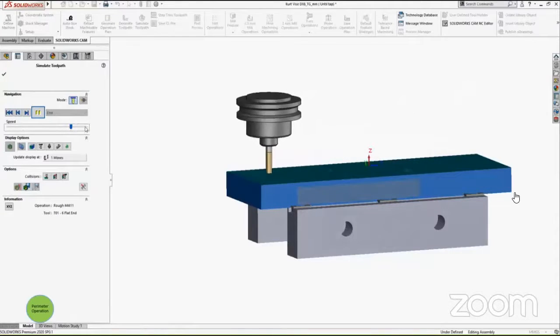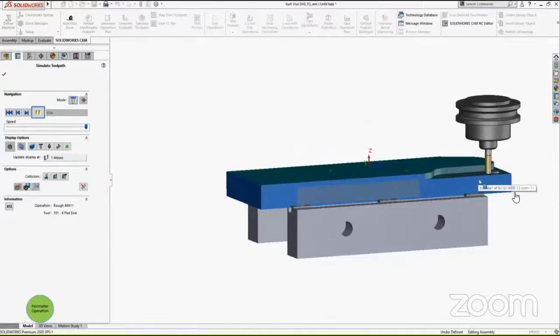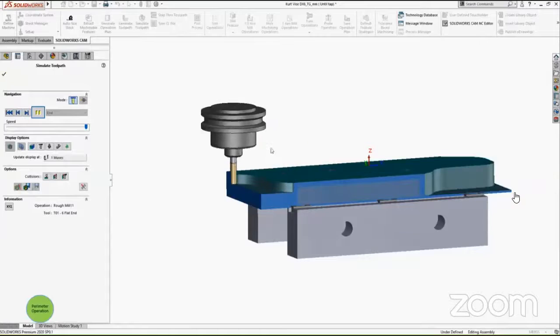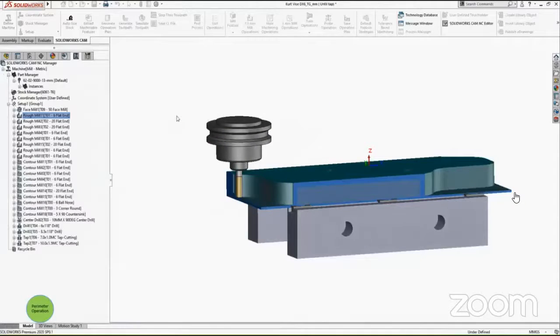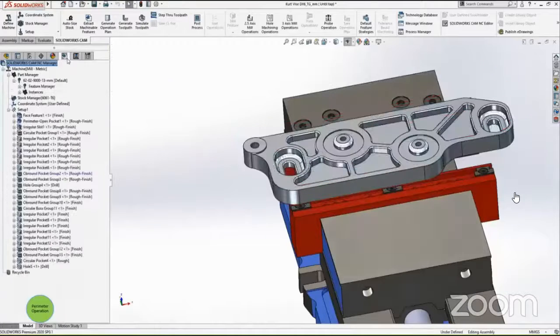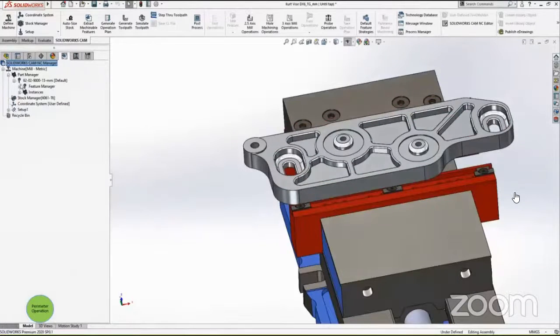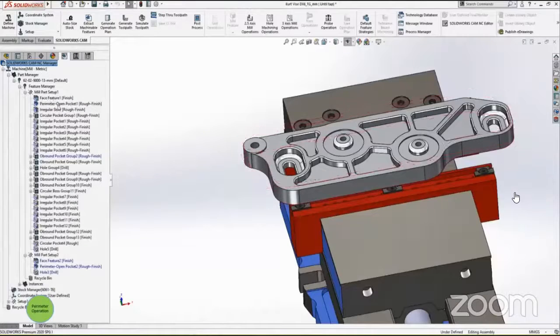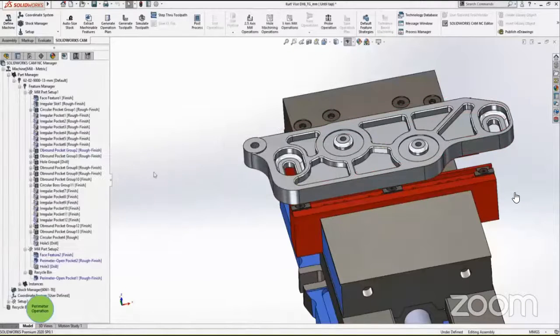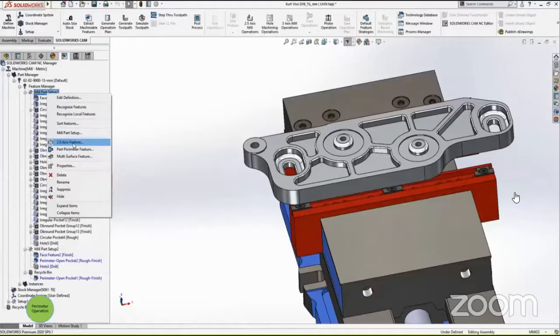So we have to remove this redundancy, and after it completes the top face, it starts to machine down the side of the CAD file. In order to remove the toolpaths from the top face, I have to remove the perimeter feature and then create my own custom perimeter features. So let's delete this one, which was created by the AFR, and I will create my own 2.5 axis feature.